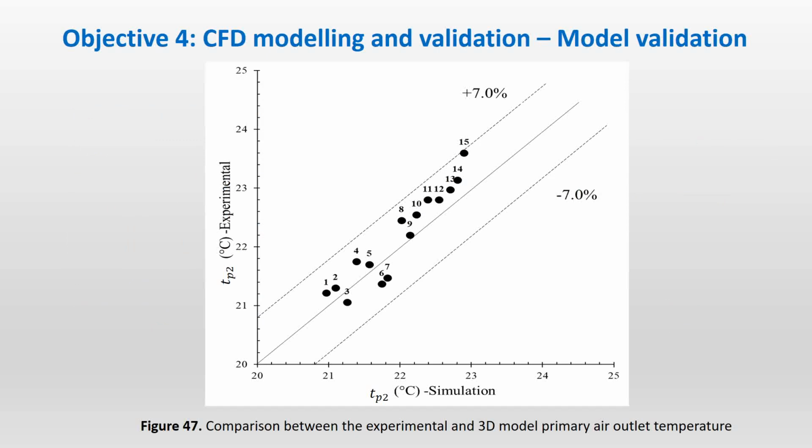This is a 45 degree line. These are the results I'm going to show you in the table when I listed everything. Actually, when we talk about the indirect cooler in real life, this is a very complicated operation because we have a wet channel, multiple sprays, and the evaporation happening. We assume that the case in the experimental work is fully insulated, but it's not. But when we say it's fully insulated in the simulation, it will be. That's what made these changes in the reading. The simulation is the ideal case, but real life is anything but ideal.